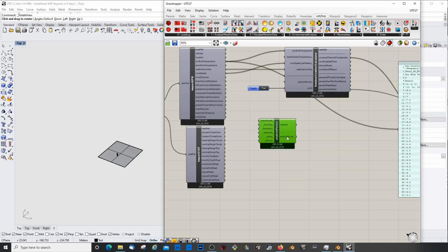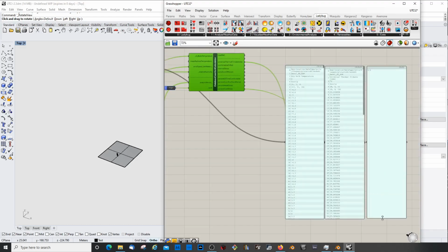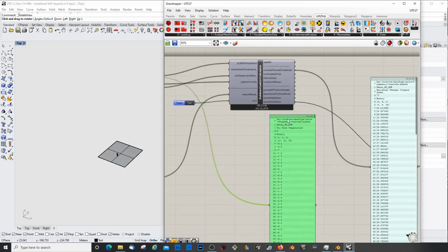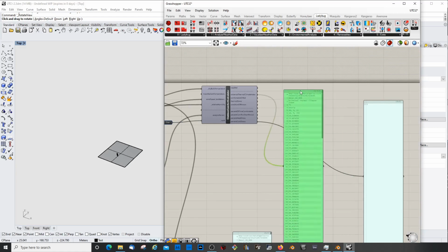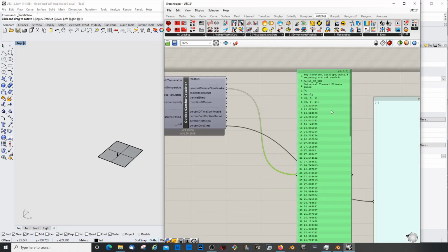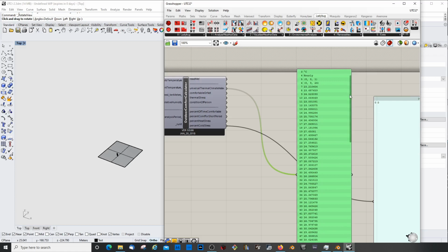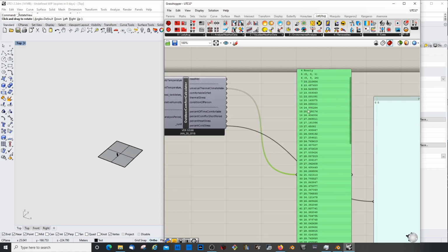The analysis period, in that case, is 1 year. It gives you the beginning date and the end date as a list. So in our case, we can just use the extreme hot week as our analysis period, or any of these. And now we cannot really compare this anymore, because this shows the whole year, but this now gives you the output only for that week. So it also shows the week, and this is the hottest week in the year. And you can see it's all above 20 and 27.